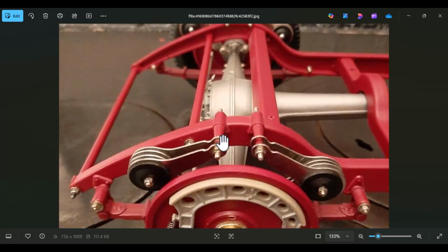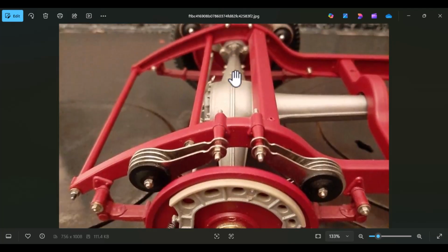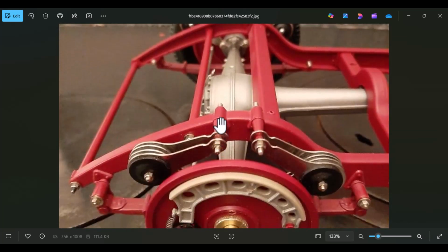We can have a larger diameter, extending it, pushing it outwards, and then a slimmer diameter where we are going to attach those friction dampers, so that we are pushing them towards the end of this differential connector, or the differential housing. And therefore we have some leverage here. We don't have to push it all the way.